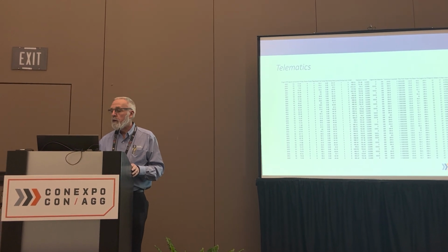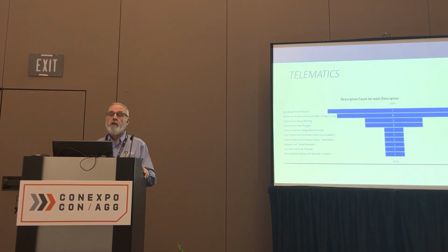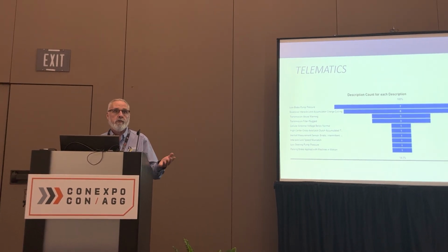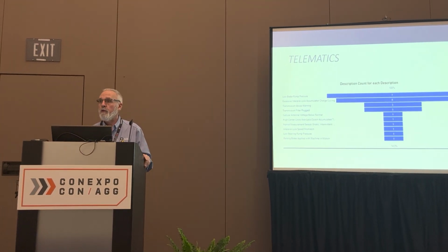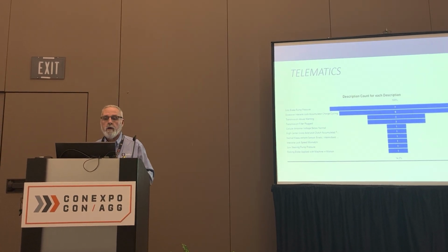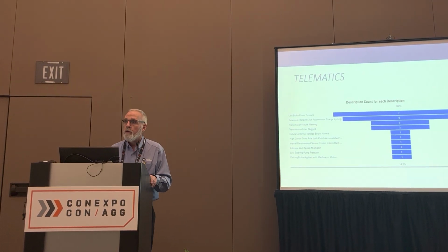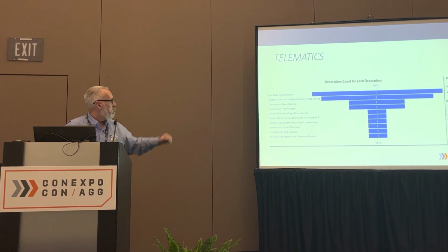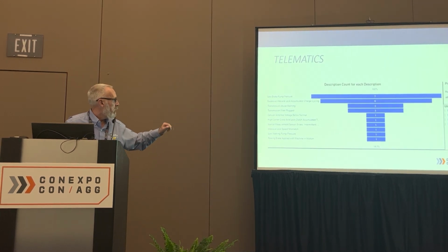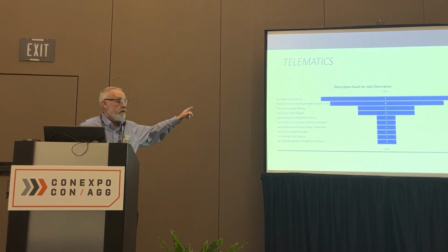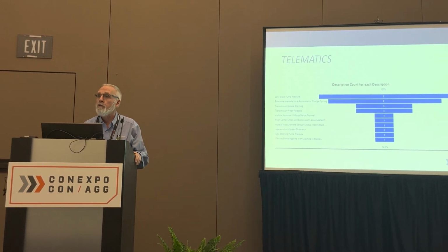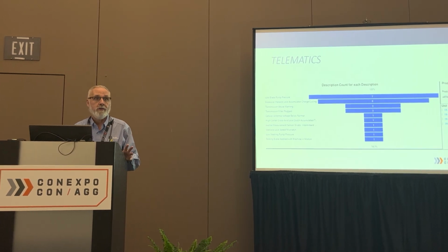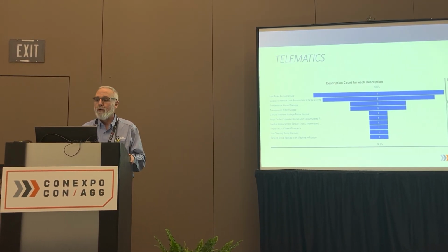So I experimented a little bit, and I was able to return this back to the customer. I said, how would this be for your telematics data? You provide us a flat file, we'll turn it into some fault trees, and we have some terrific drill down capabilities here to understand what the telematics mean. And we can see here low brake pump pressure, excessive interaxle lock accumulator. This was a huge one, transmission abuse warnings. That's great to know, right? Because then you can go back and talk to the operator that was operating at that time.